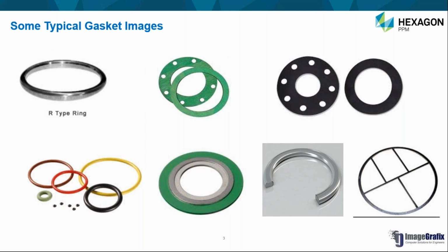Your gasket surface will have higher thickness in case of inner and outer ring. And this is the surface which, under pressure, is going to compress, and hence the leakage will be avoided. The second last one is your kammprofile type of gasket. This is again a metallic gasket with filler in between. And the last one is the gasket which we basically use for heat exchangers for the passes. So these are the various types of gaskets generally used.